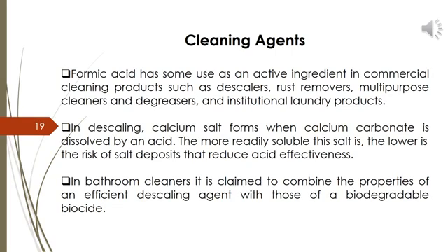In descaling, a calcium salt forms when calcium carbonate is dissolved by an acid. The more readily soluble this salt is, the lower the risk of salt deposits that reduce acid effectiveness.